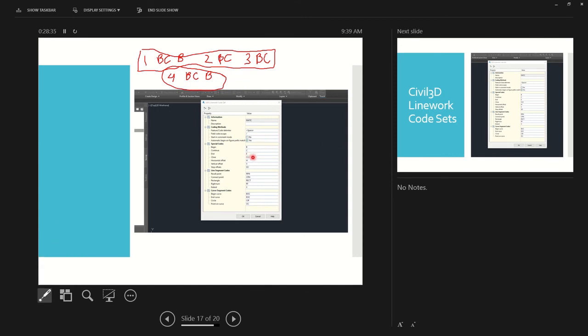Okay, so there's that close command that we talked about. And we can also do horizontal and vertical offsets. I've never used those when I was out in the field because our equipment nowadays will do a vertical and horizontal offset for you, so you can actually key that in prior to even putting the code in there. Same with stop offsets. You don't have to use those. The information on the line segment codes, we don't use that very often anymore because it's all stuff that's controlled by the data collector.